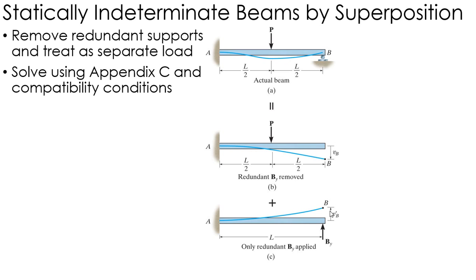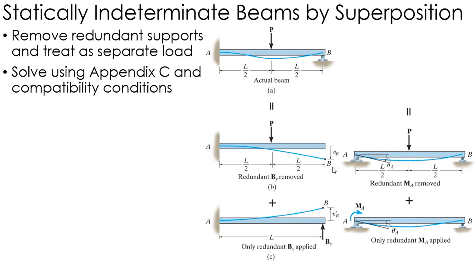Now, I can actually set these up in different ways. I could also treat this as a simply supported beam with a load in the middle and a moment at the end point, because again, my cantilever is both a load as well as a moment. Okay, and then knowing specific things, I can go ahead and calculate that. I can know that the slope at the left side is 0 for the beam here, so I can set that slope equal to each other to solve for that.